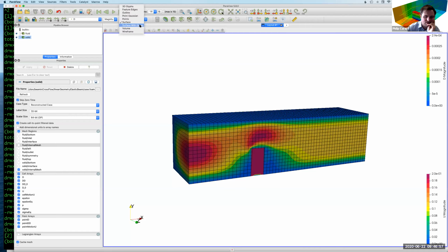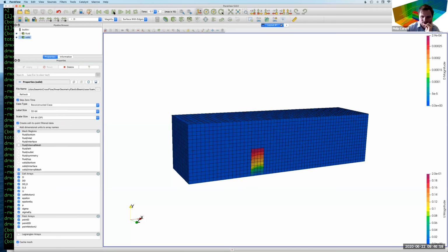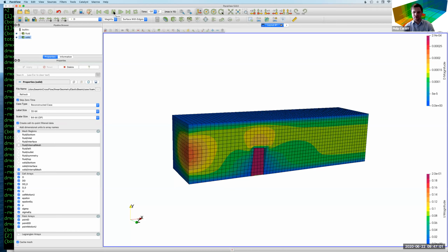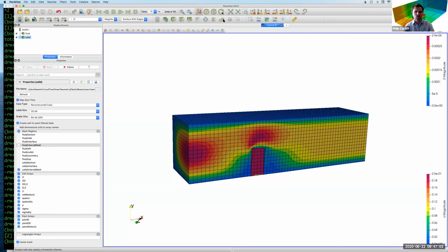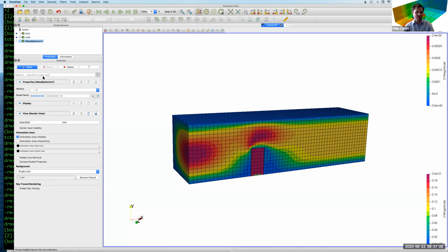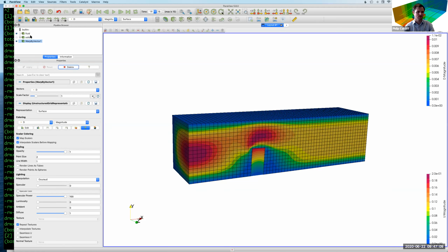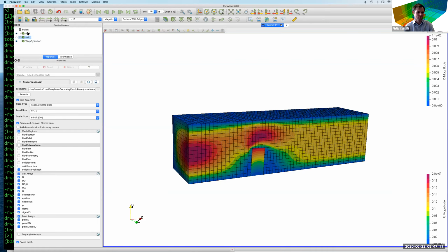Let's turn on the mesh. You can see the solid looks like it's not moving, but it is calculating the motion and passing that to the fluid. So we just need to warp the solid. If I warp it by the displacement field, multiplied exactly by 1, then you'll see it all lines up fine, assuming that they're both refreshed at the same time step.